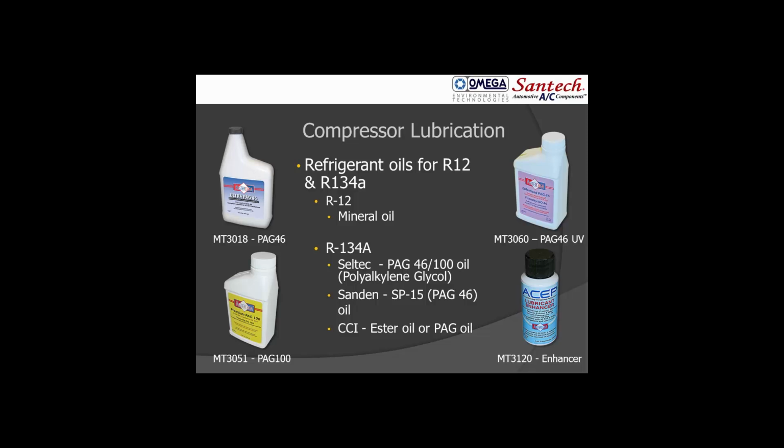The oil itself, there's several different types of it out there. Back in the R12 days, we used mineral oil. It was a very universal oil. As systems converted from R12 to R134a, we got a new refrigerant, so we started getting new oils. Started out as an ester oil. Ester oil has pretty much gone out of style these days, and all of the compressor manufacturers are recommending and using a PAG oil, polyalkylene glycol.